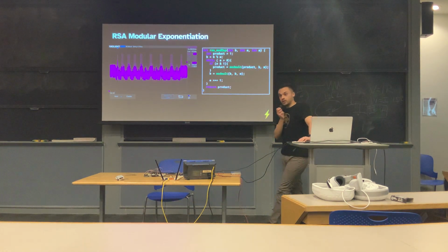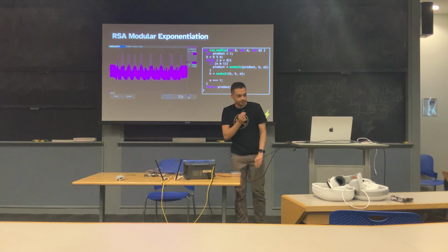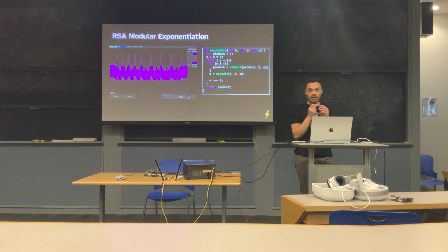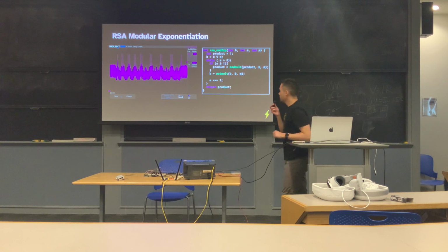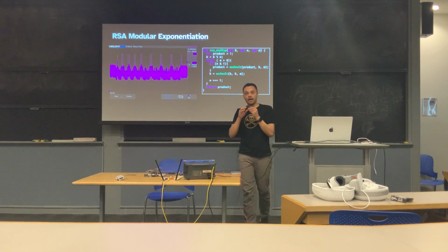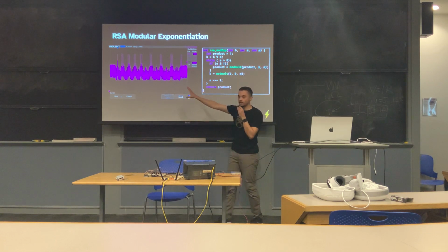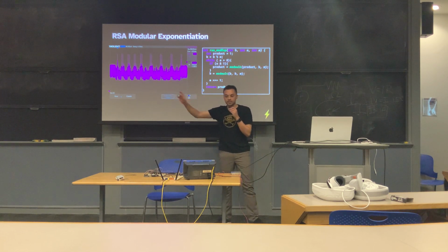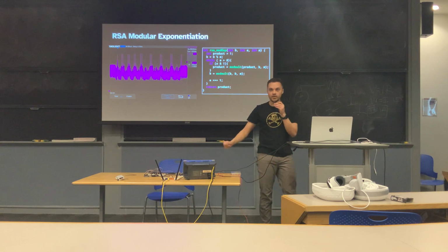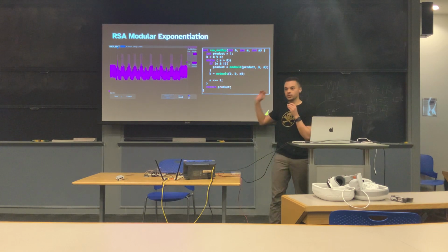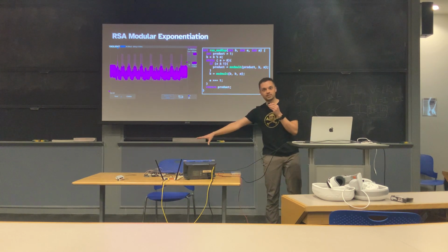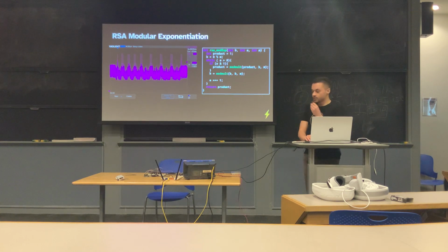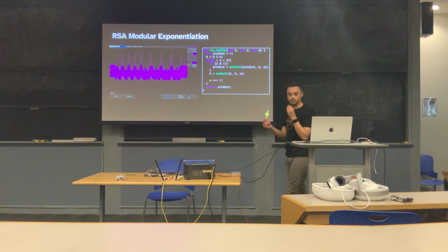The victim of our attack today is going to be RSA. Here on the right, I have broken out a little bit of what RSA is going to do internally. And on the left, we have a trace I collected on the scope beforehand. What I want to do is walk through the algorithm with you, show you how to learn what RSA is doing from power traces, and then we're going to do it for real on the scope and see if we can, as a class together, learn the secret key that I've embedded in this processor that you don't know.